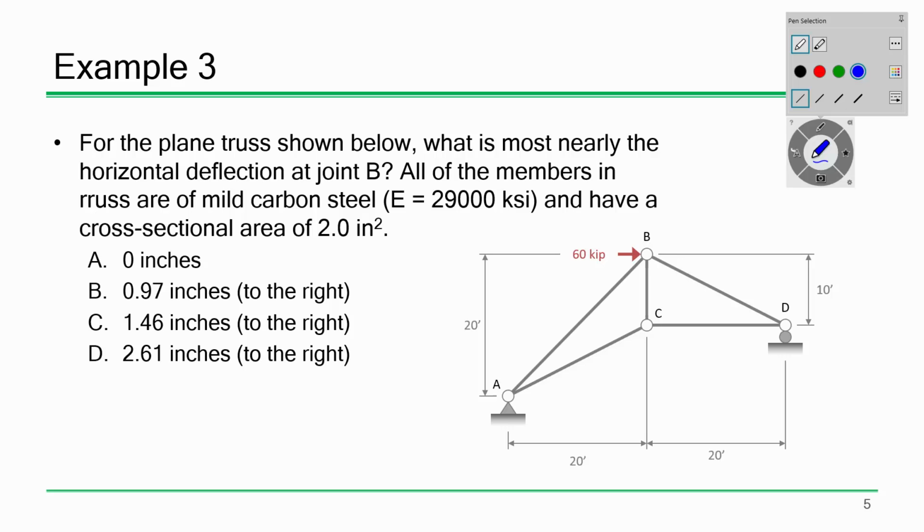But one of the things you'll find about it is it ends up being kind of rote, and there's a little trick to this particular example that makes it a little easier. When it comes to deflection problems for trusses, there is only one way to do it effectively, and that's the unit load method, where you take a 1 kip load and place it on there. So we'll review that. For beams, there are 3 ways to do deflections that I think are effective. Number 1 is double integration, which I'm probably not going to cover, but we can talk about it later or at another time if you're interested.